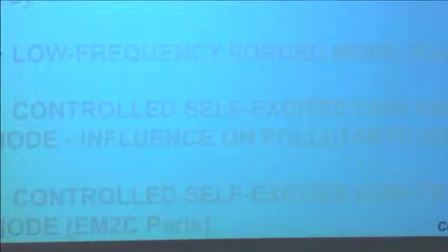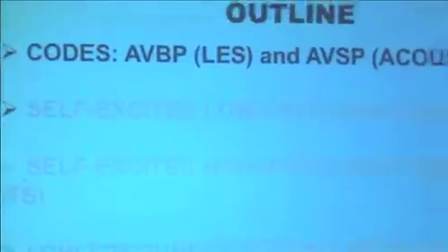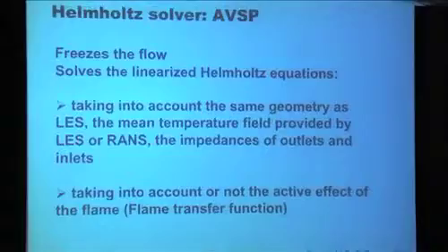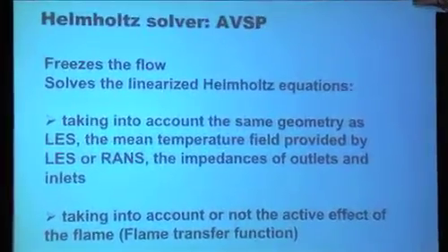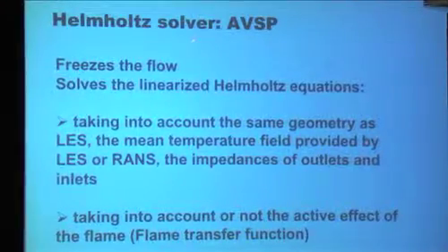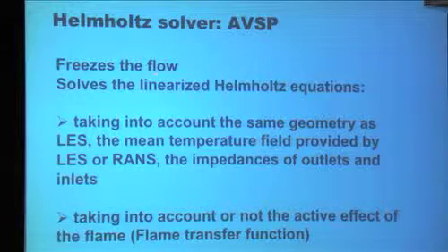So I want to illustrate that on a few examples, just to remind you that we're going to be using the LES code I've presented before, and we're going to be using a Helmholtz solver, an acoustic solver, which is following what I've said before. We freeze the flow, we solve the linearized Helmholtz equations.